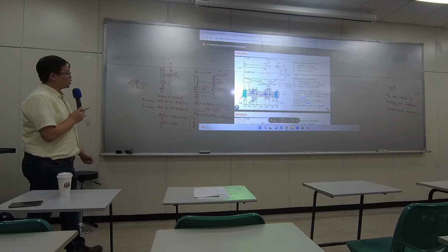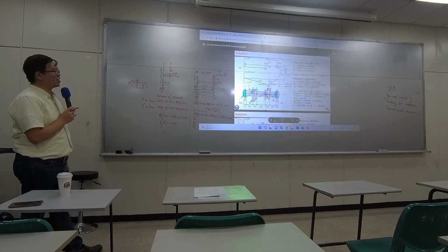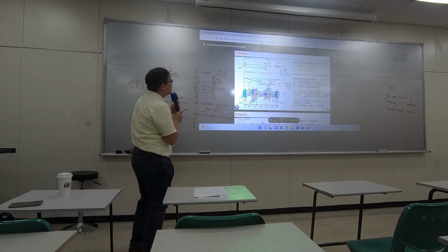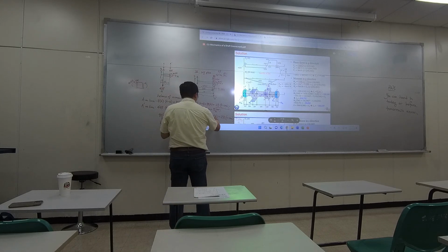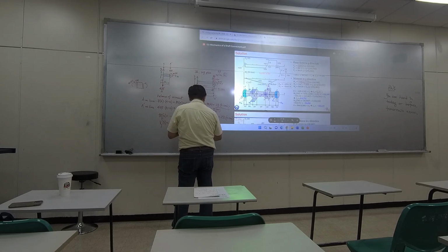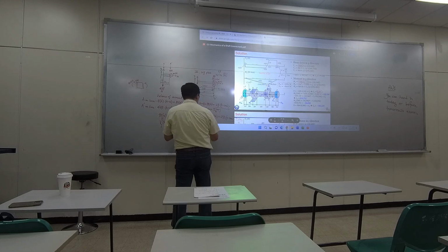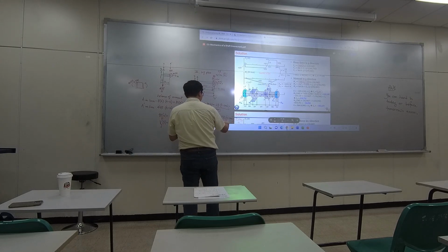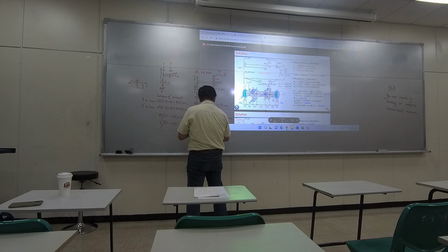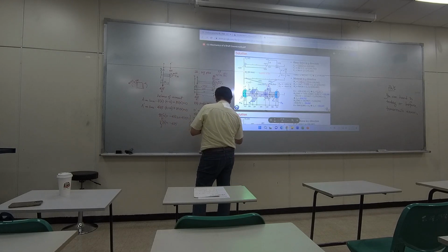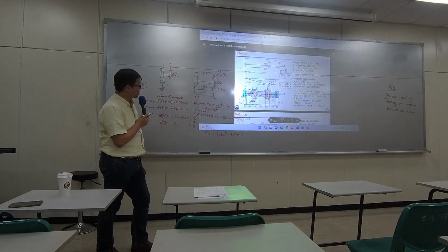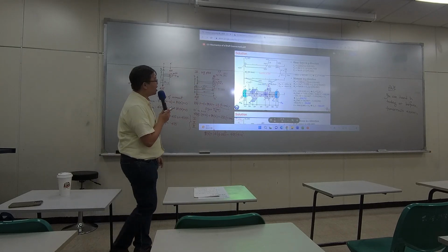Solve for those, you will get your M and V. So let's try your Mx first. Mx is going to be whatever you have right here, basically 14 times (x minus 240) squared, and then minus 435 (x minus 10). That's basically it.